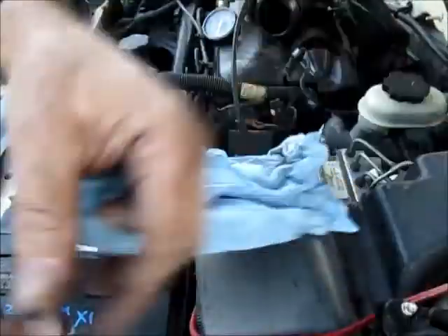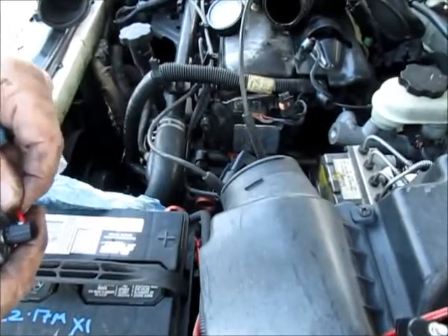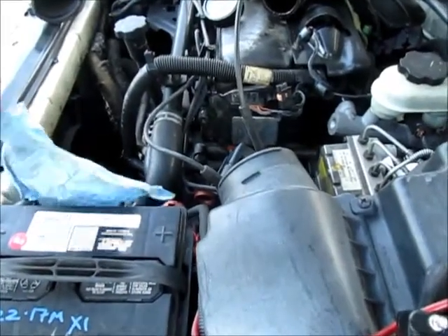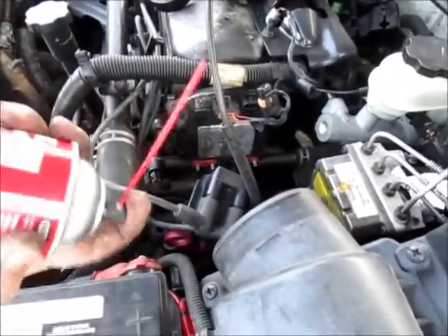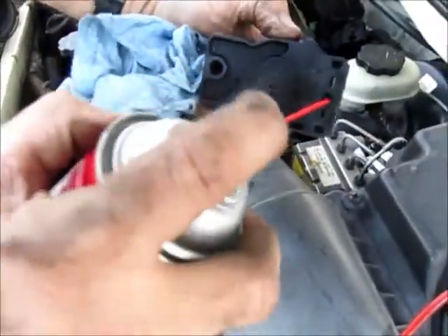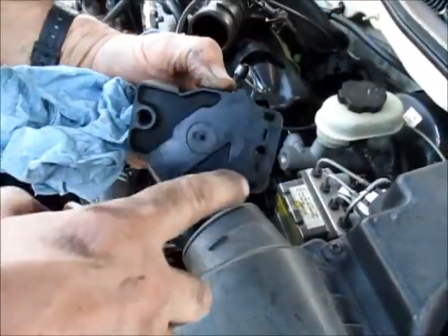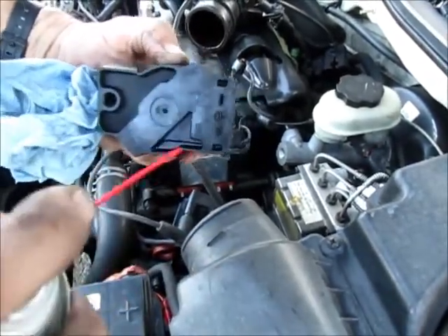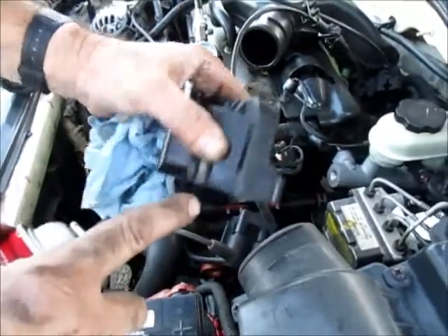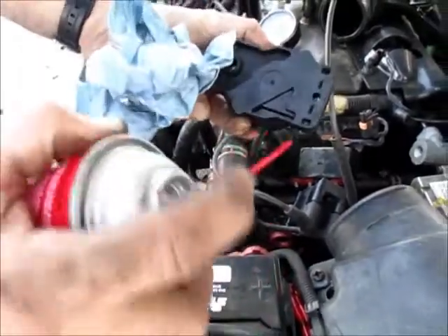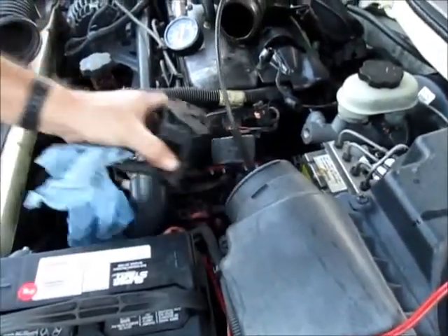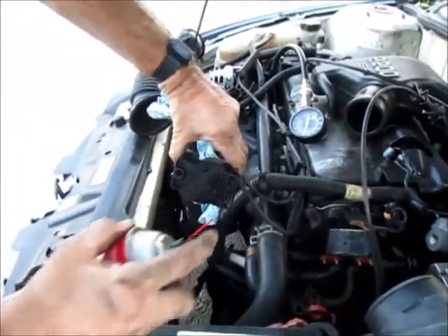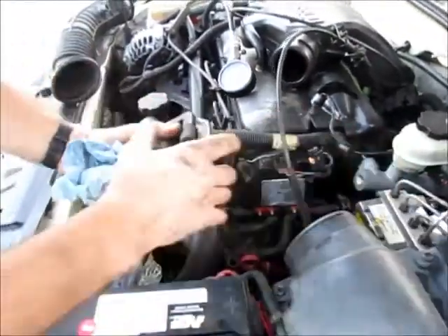The first thing I'm also going to do is, since I got a lot of oil down in here, I'm going to clean all that off. So we get your electrical spray, and then in here. This had a lot of oil, so if you have oil in this, that could possibly cause a bad connection and also cause our problem. So the coil might not even have been the problem itself. It might have been these primary connections causing the problem getting current to fire the secondary part of the coil. So we're going to spray this out here. Do this one too while we're at it. Okay, let that drain a little and dry out.